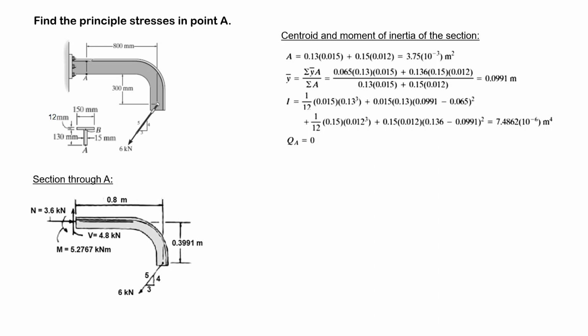Now, to determine the internal loadings, we have to cut, and when we cut over here, possible internal loadings are a normal force, a bending moment, and a shear force. So we do not know these values.